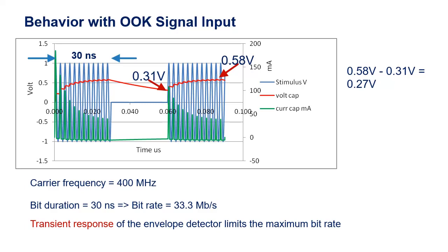However, please be aware that you cannot make C too small as then the ripple becomes excessive. Same applies to R2 as well. Making it too small may make the output voltage unacceptably low. In a practical situation, there may be more than one off or on bits successively. This needs to be taken into consideration when designing a practical system.